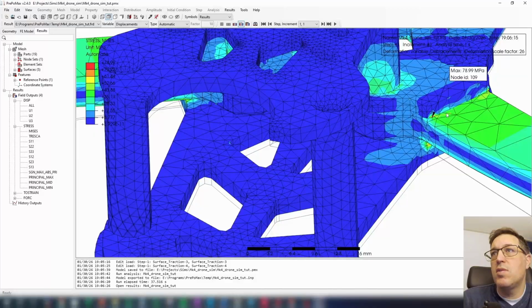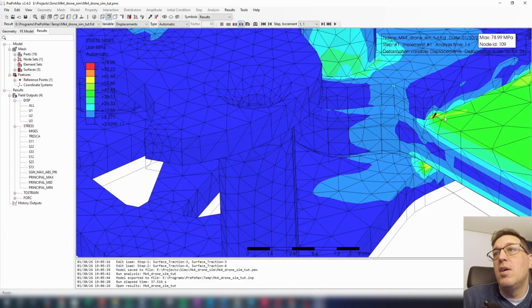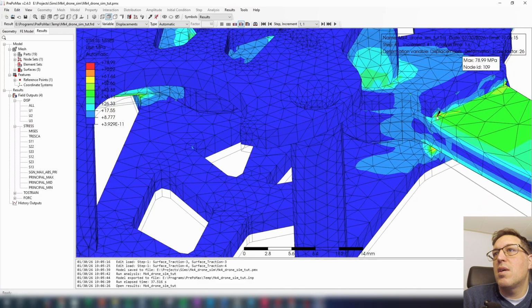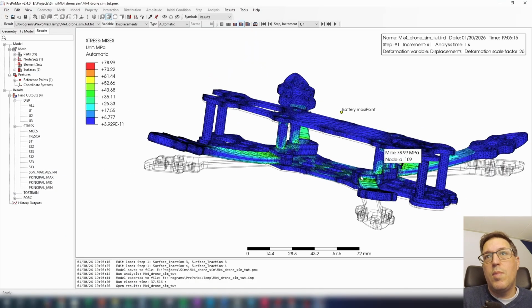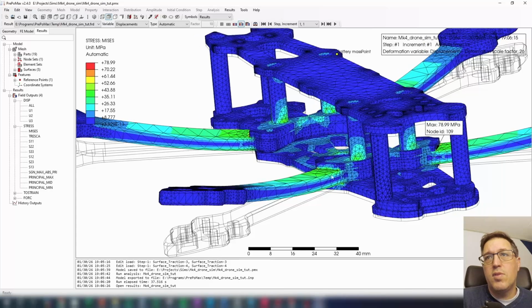It's just a very high spot. What interests us is this area. Yes, we need to take into consideration this one here. But this can also be an artifact due to the way it was meshed at that point. And what I would do next in order to eliminate this artifact is to refine the mesh in this area, specifically this area. Again, I would make some rough calculations about a beam under stress with a section cut.